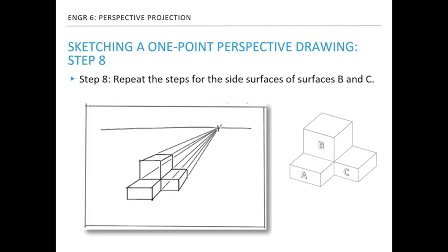Here the key point is that all the recessed lines that are parallel to the view direction, or normal to the image plane, should be drawn towards the vanishing point regardless of their starting points.